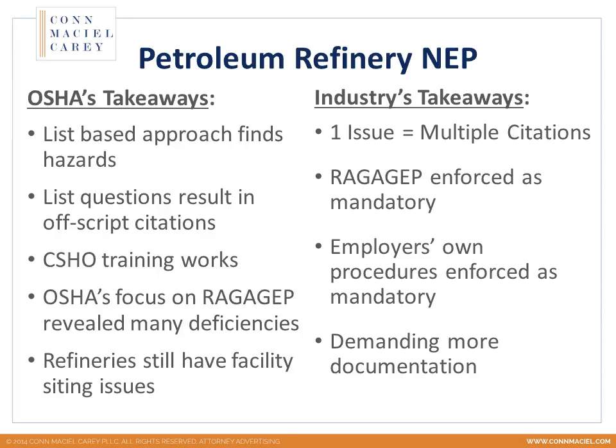Likewise, OSHA is treating employers' own procedures and own written policies and programs as mandatory. And that, I think, is a little bit less of a stretch because the PSM standard is what's called a performance-based standard, which means OSHA is not going to prescribe how you do it, but they're going to tell you what the goal is, what the performance objective is, and then you are required to implement a program and policies and procedures to drive compliance with that objective.